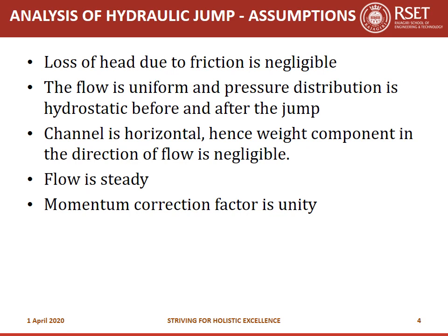We are considering the flow to be uniform and the pressure distribution to be hydrostatic before the jump and after the jump. That is, the supercritical flow before the jump is uniform with hydrostatic pressure distribution, and the subcritical flow after the jump is also uniform with hydrostatic pressure distribution.